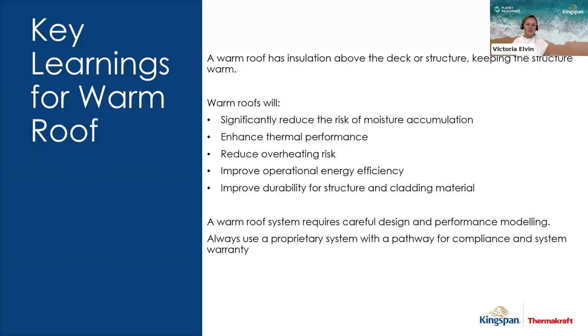But a warm roof system does require careful design, and it does require performance modeling. Always use a proprietary system with a pathway for compliance and a system warranty.